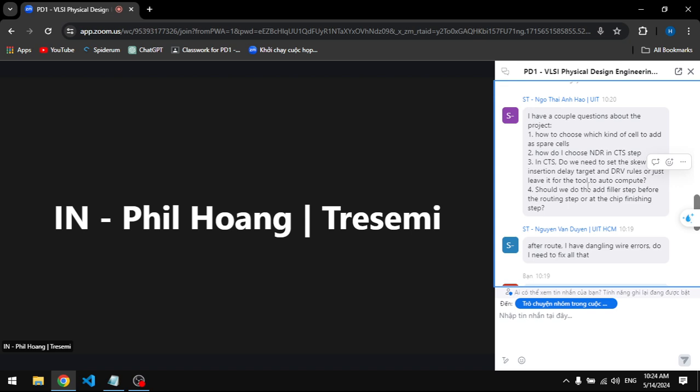And double spacing deals with crosstalk, right? If the clock net is an aggressor, and you have signal nets that run parallel to it, the coupling from the clock net can disturb the signal and cause glitches. To help with that, you space the signals from the clock nets so that you can reduce coupling effects, and therefore reduce glitches.